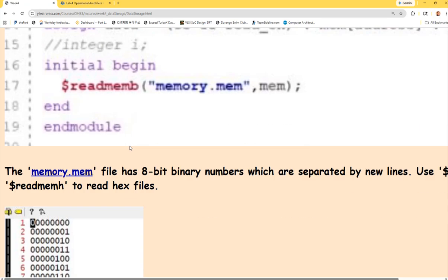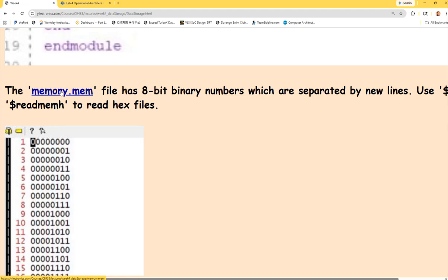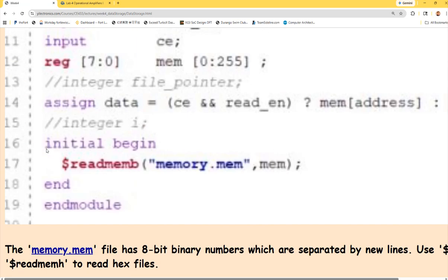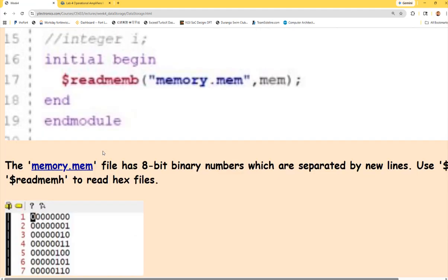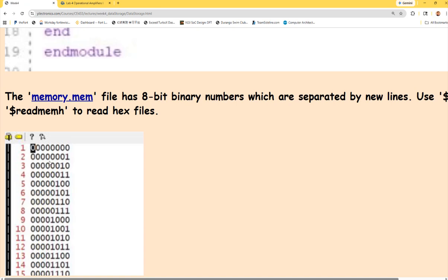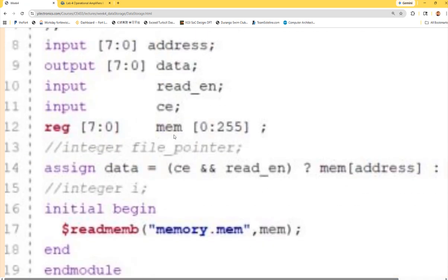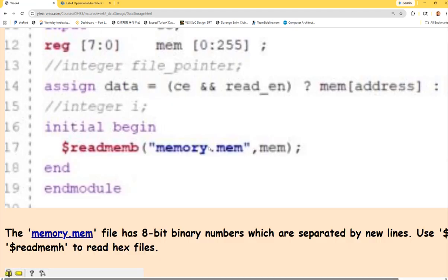So what this does is, the memory file is something you typed into the text editor, and when this is read, they store them into a register data type in your hardware. You can just imagine these are probably just different flops, just latches. They are being latched. So the data file in the ROM you typed as text will be latched into a register type memory by this line of code, right?